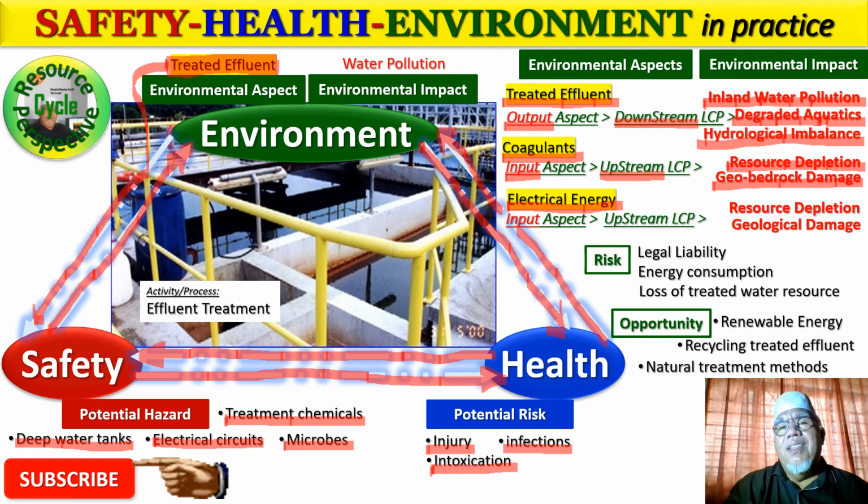But on the other end, when the nozzle is smaller, more pressure is needed. In order for that pressure to build up, you need to have more power from the blower. The blower pump has got to pump harder, stronger, in order to have those well-diffused bubbles of air in the aeration tank. And that's a lot of energy. On top of that, you've got control panels, flow meters, pumps, vortex pumps, positive pumps, dosing pumps, etc., and lightings, of course, for the control room. We got to work at night, right? In the night shifts. And these are all electrical energy.